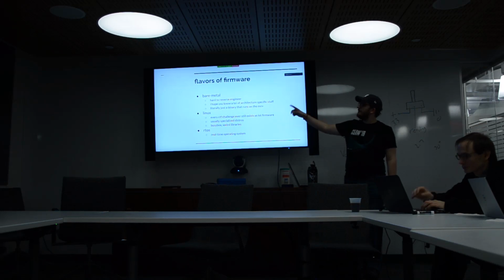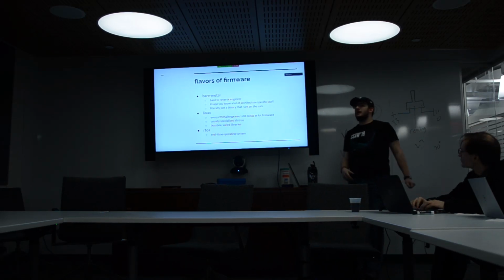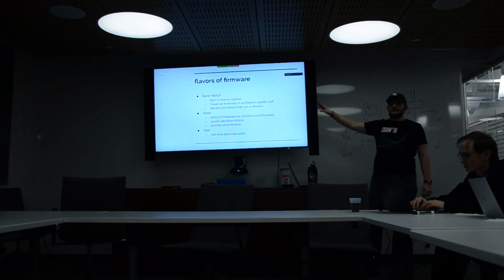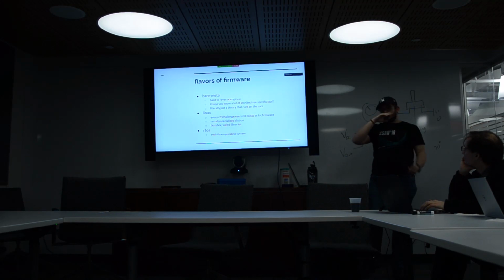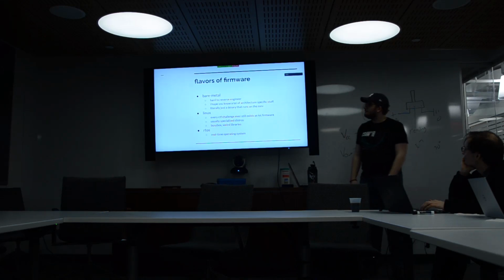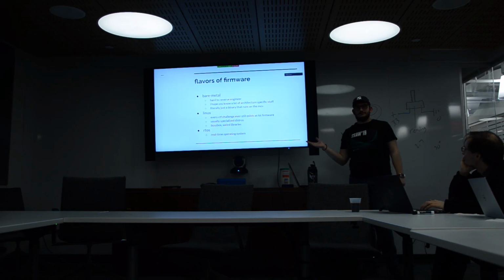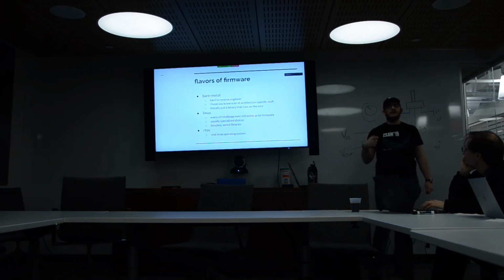And then you have bare metal real-time operating systems. Bare metal firmwares, which are literally a binary that is compiled and targeted at that particular microcontroller that the bootloader just yeets into memory and sets the instruction pointer to, and it goes. Hard to reverse engineer because it's very, very, very architecture specific.